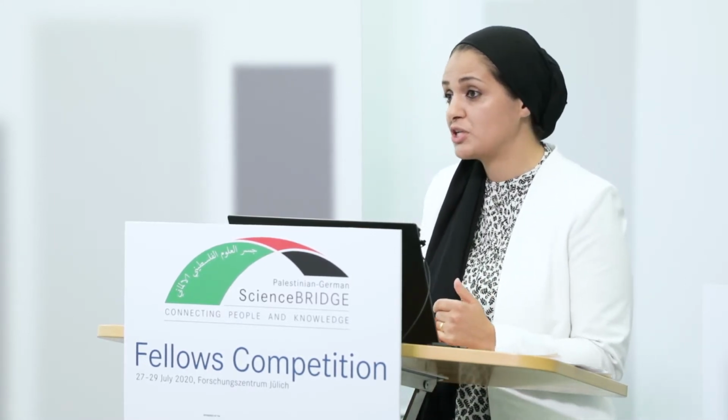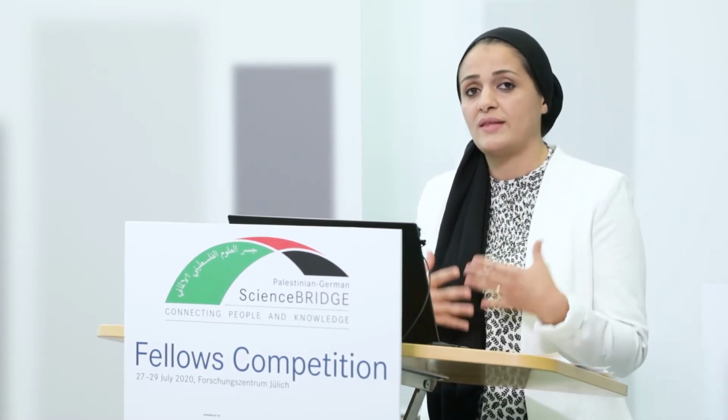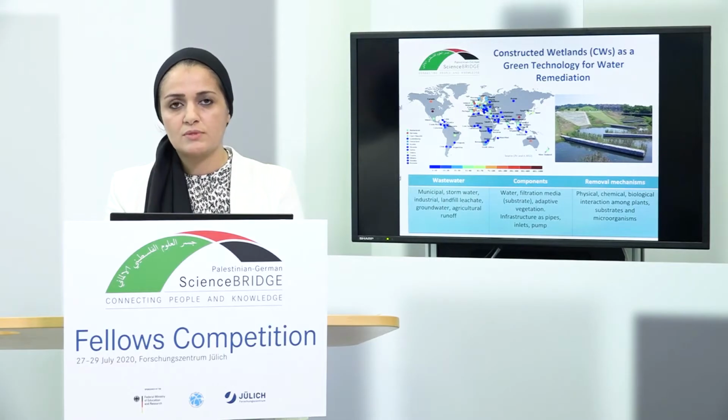The removal mechanisms involved in constructed wetlands for removing the pollutants are physical, by precipitation of the pollutants on the porous media, or what we call the substrate, and I will come to this later in another slide; chemical, like ion exchange; or biological, like degrading the organic matter by the microorganisms and uptake of the pollutants by the plant.